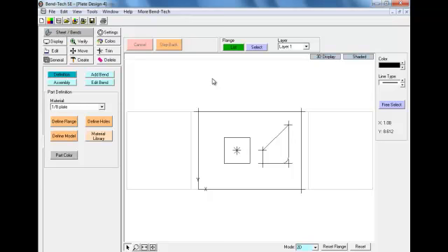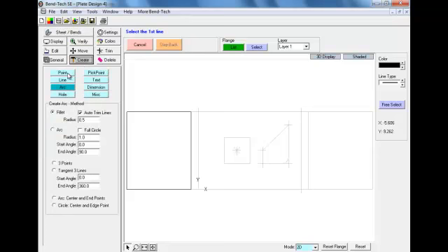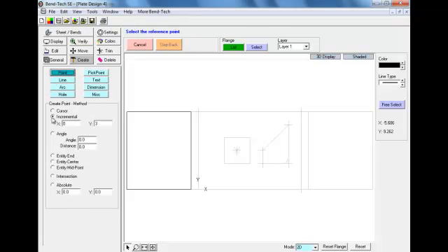Once we have both of those holes created, we need to redefine that flange. We'll do that by hitting the Sheet Bends tab, the Definition button, back to Plate, and define the flange. We can now create our holes in our end flanges.